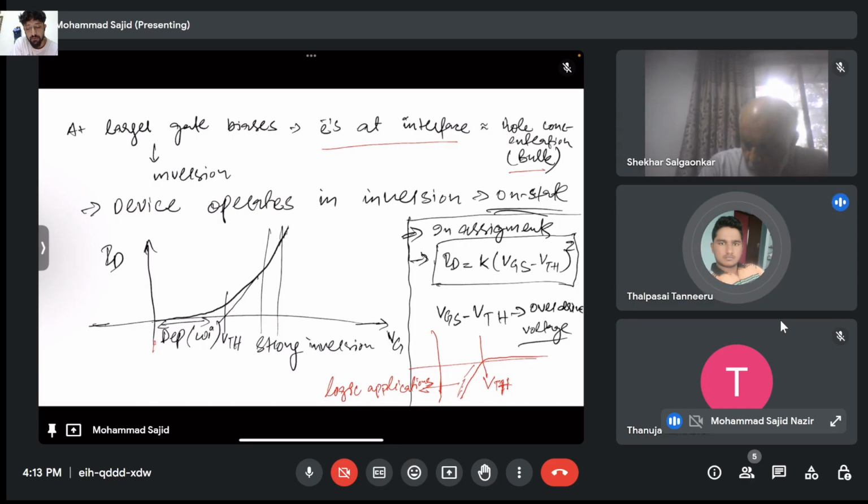So you have to optimize. For example, you can connect multiple stages in cascade, not cascode, to increase the gain. Instead of a single transistor, you can use multiple transistors at lower current levels to get the final output that will give you the desired gain.